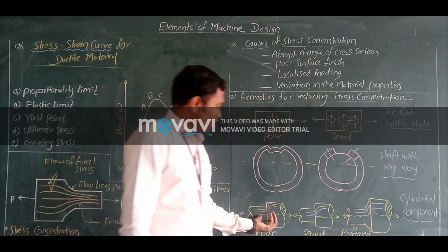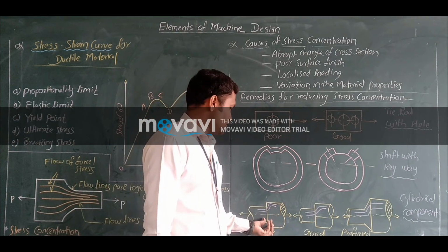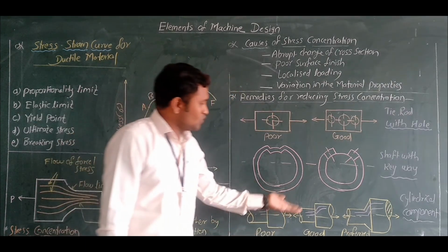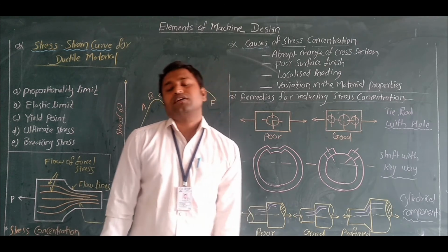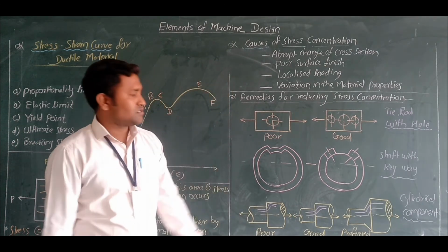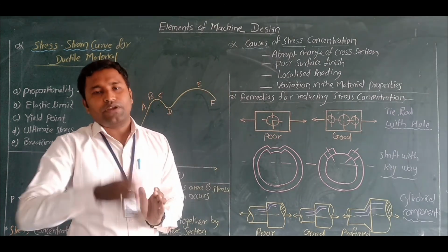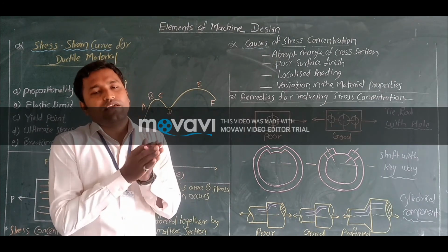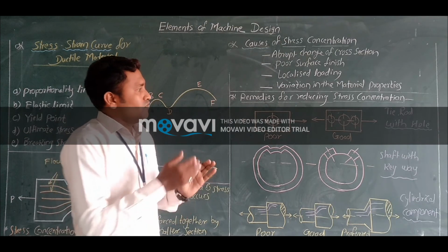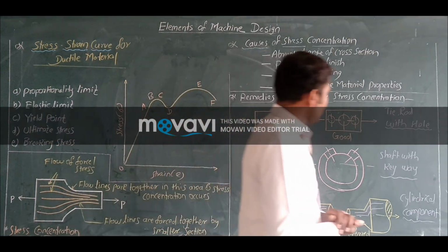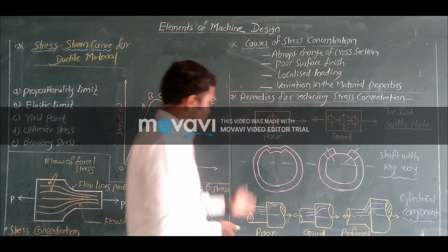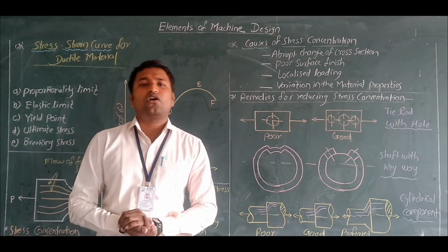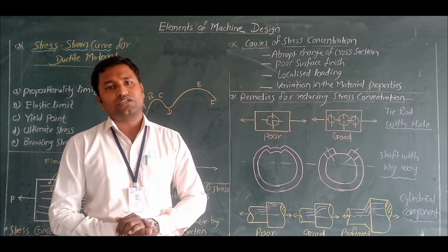Sharp corners should be avoided by replacing them with a fillet, some radius, so that the stress concentration is divided.